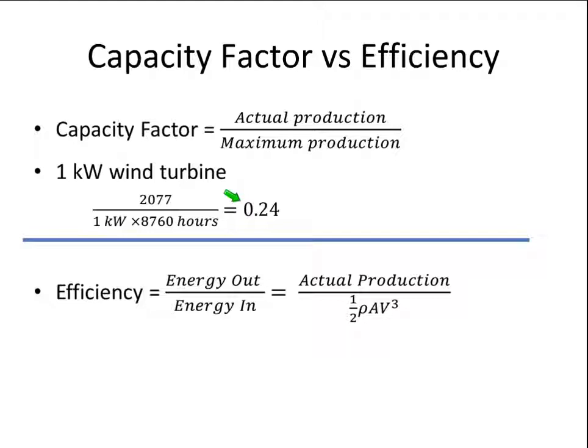For a large wind farm, for the whole farm, a capacity factor of, let's say, 45% would be very good. While the two wind turbines here on the north side of Lincoln have a capacity factor of about 25%. The problem with those two is that one is put in a better wind location than the other. So your wind location has a lot to do with that. Your turbine itself has a little bit less to do with it. The reason your turbine might have an influence on capacity factor is if you broke down.